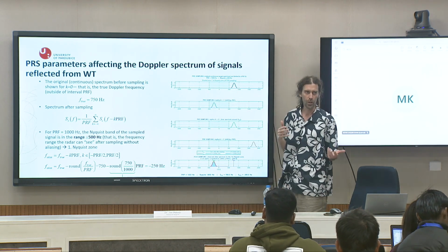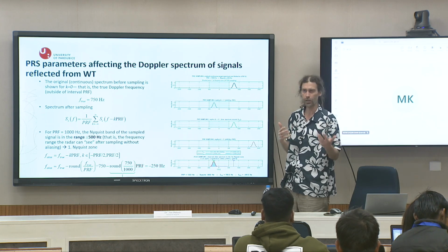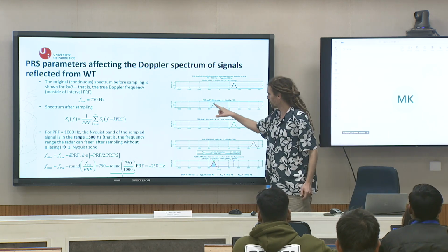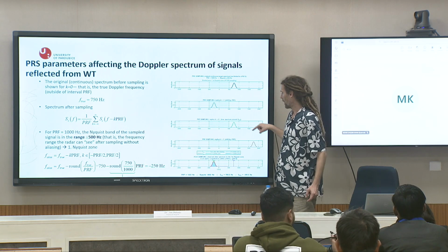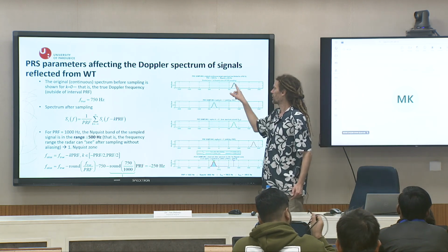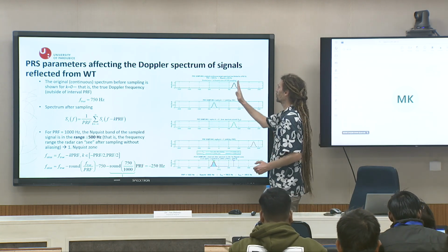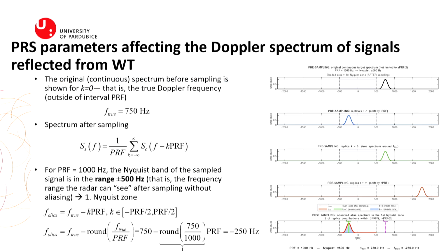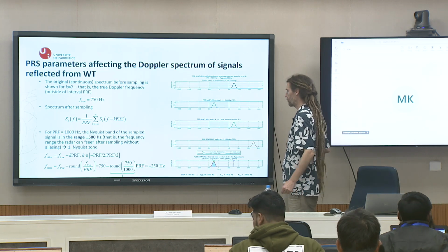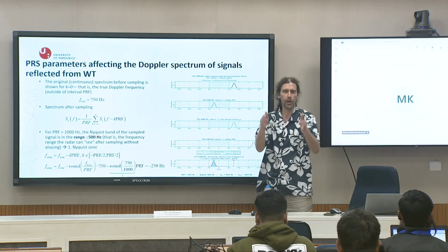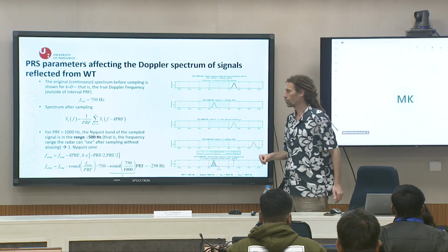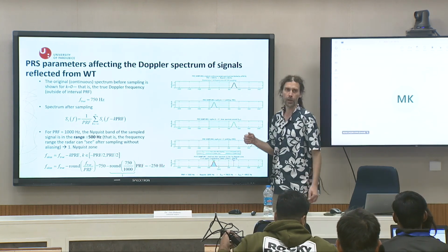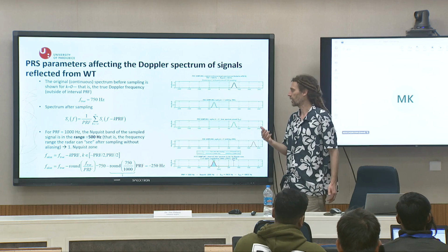So what happened? Of course, aliasing of the signal happened. This is a presentation of replicas of this spectrum, because this is the original spectrum. There will be -1 replica, -2, -3, -4, and so on, and the original 1, 2, 3, 4, and so on, because the spectrum is periodically repeated due to aliasing. How will our signal look?